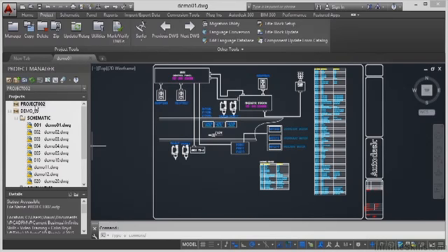What I've done is I've set up project 002. That is also in the work files folder at the moment until I delete it. Make sure that when you delete a project you don't just go to the Windows folder and delete the project there, because it will still be in the database for AutoCAD Electrical, and that can cause lots of orphan issues for things like project links, drawing links, attribute links and so on.